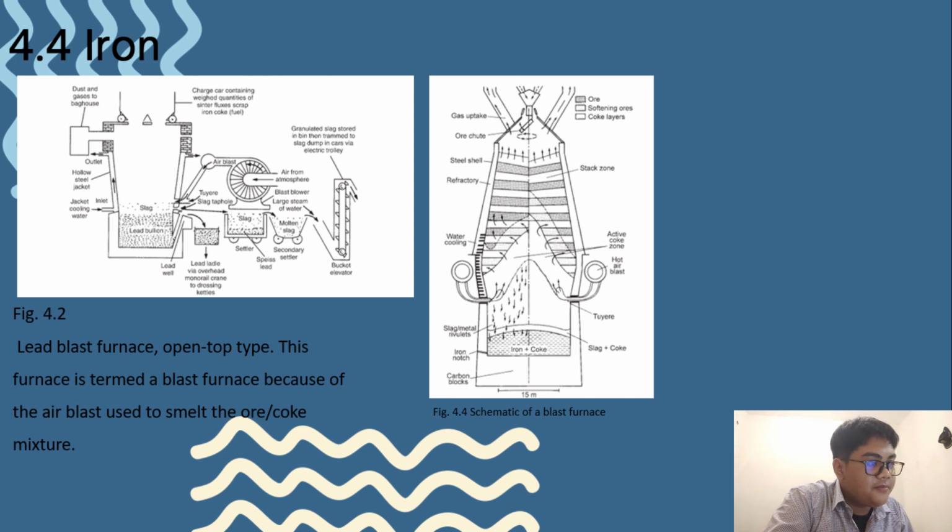The first iron to be developed was wrought iron. Wrought iron can readily be forged to shape. In fact, the term wrought means to shape by hammering or beating. Wrought iron is very ductile for forging because it contains very little carbon, less than 0.05%. Carbon is an interstitial impurity that strengthens the iron lattice. In fact, iron alloys that contain between approximately 0.1 and 2.0% carbon have a special name. They're called steels.